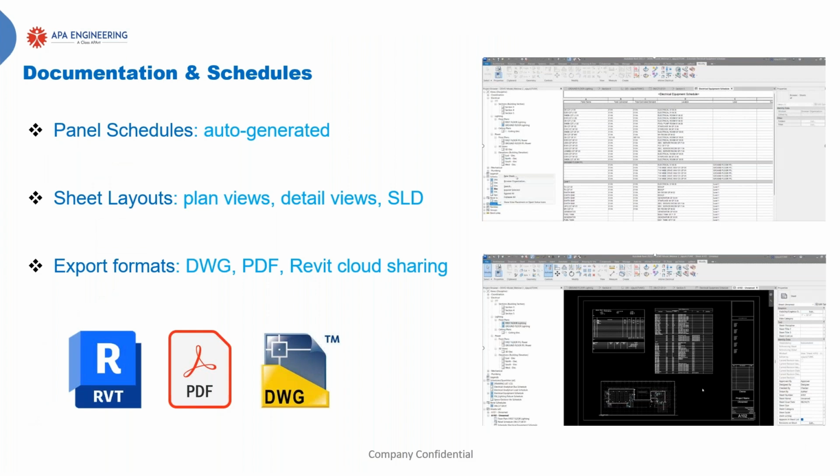Documentation and schedule. Panel schedule. In the demo video, we saw the automated panel schedule, correct? So with just a single click in the panel, we generate the automated schedule. For the sheet setup, we just drag and drop the sheets from the model to the sheets.